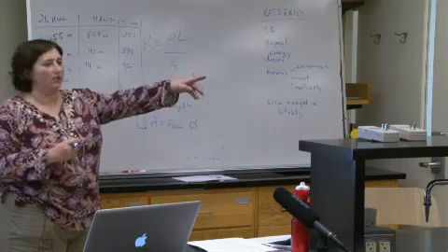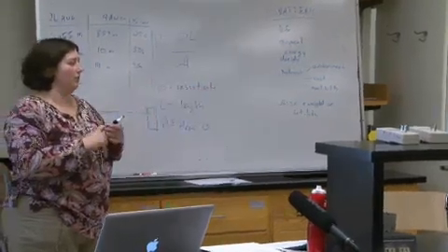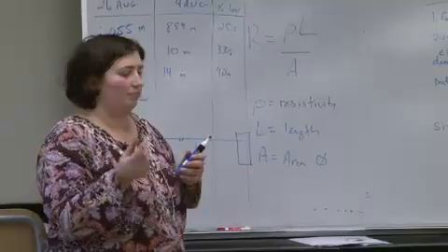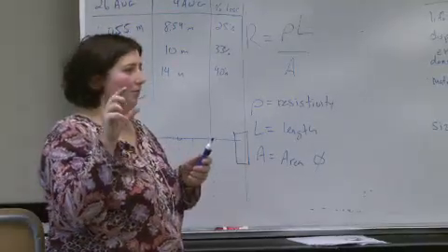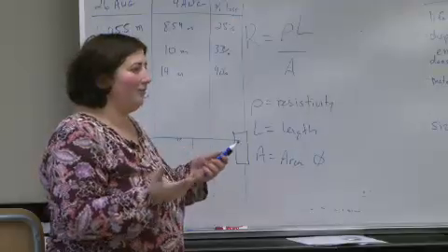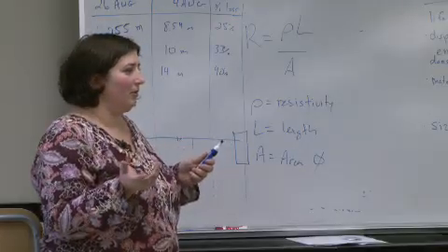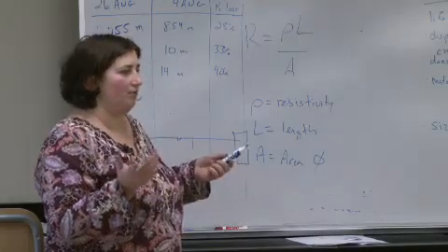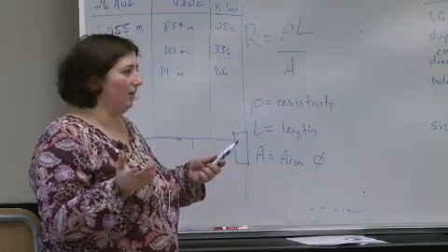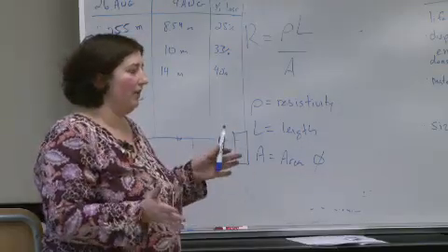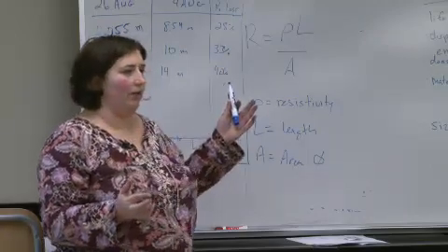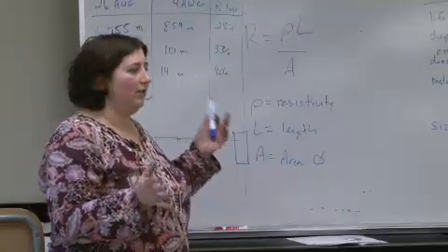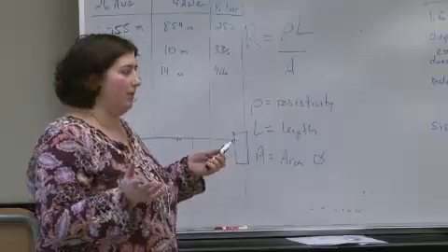And one of the things that's really interesting on your lanterns is that a lot of you didn't use wire. You used found materials like paper clips and binder clips and all the variety of things which have decent resistance, and yet you have an LED that's pretty robust to high resistance, and so it worked fine. So that is one of the nice things to think about: yes, you're getting losses there, and if you want to perfectly maximize the light output of your LED, then you need to worry about it. But if the losses are relatively small, you're fine.